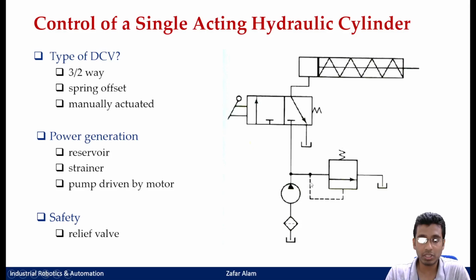That means the pressure starts to build here. Okay, this is a two-way valve. This is the inlet of that valve and this is the exit port of that valve. The spool is generally not aligned to this inlet and outlet. It is generally kept at some offset, and that is engaged through spring pressure here.